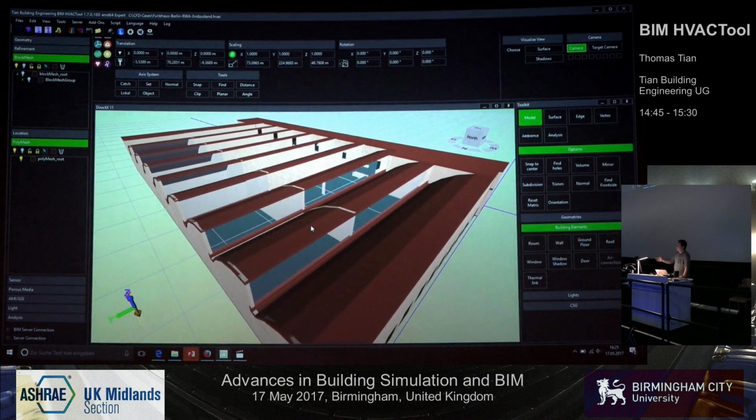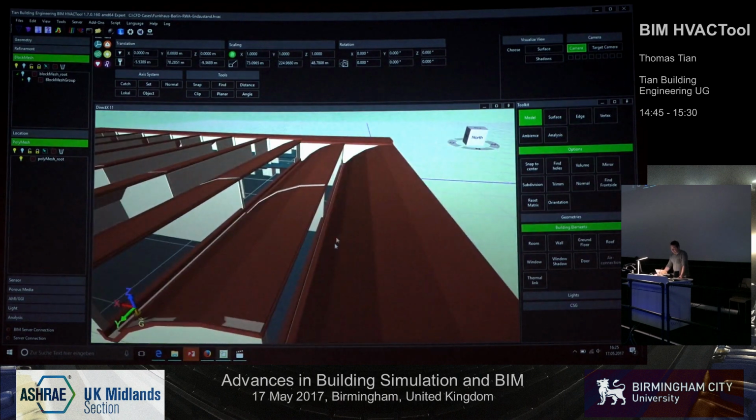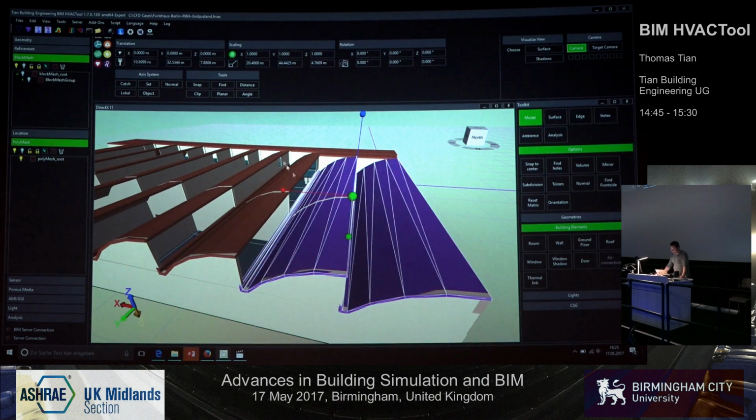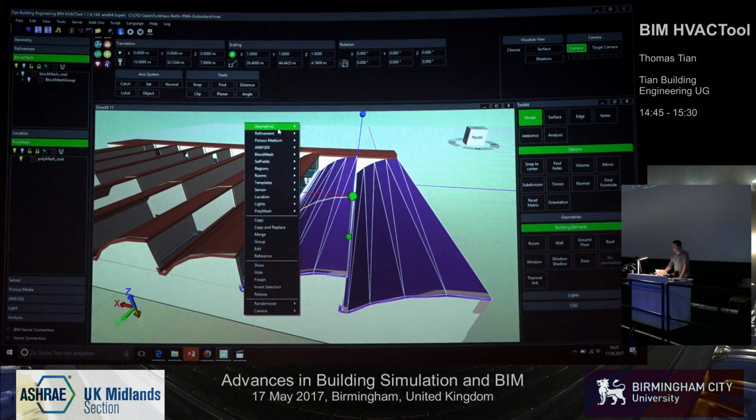If you import your SketchUp model, it is a stupid model, there's only geometry. But the software can understand there's transparency, so it must be some glass or something. For SketchUp models, OpenFOAM doesn't care about it because it also uses that stupid model for meshing. But for EnergyPlus, you need to change it to EnergyPlus. There is some function that can support you to change the SketchUp model to EnergyPlus. The good thing is that if you have done it with EnergyPlus, you can also run it in FDS and OpenFOAM. Only one model, because I cannot pay my engineers a long time for modeling.